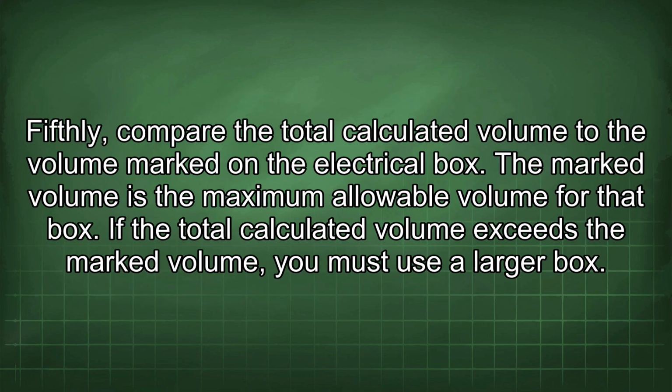Fifthly, compare the total calculated volume to the volume marked on the electrical box. The marked volume is the maximum allowable volume for that box. If the total calculated volume exceeds the marked volume, you must use a larger box.